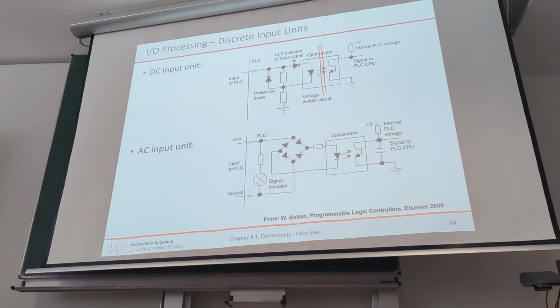That's an electrical device. And so the main reason why these inputs and outputs are more complex or more expensive than in a microcontroller is that a microcontroller just has a measurement device and that's it, a transistor, and here you have the protective circuits and the shaping of the signal, so that you get good looking signals instead of all the noise and everything.